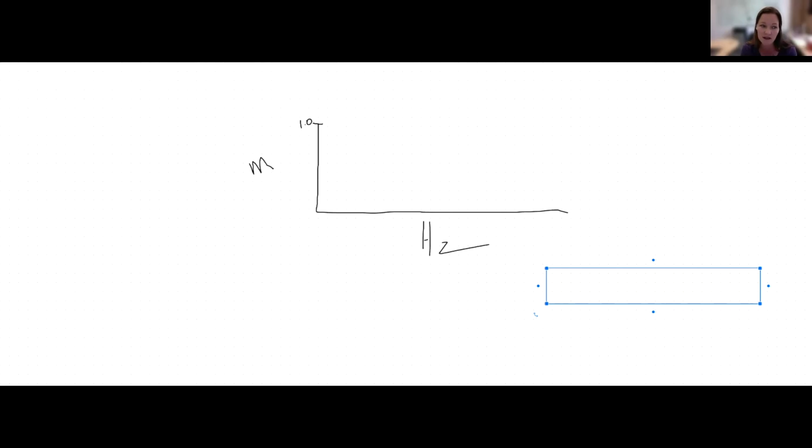Those would typically be at the frequency ranges of the motion, and so they're at lower frequencies, like below 25 hertz. The other common source of noise that you would find in many signals is electrical noise by picking up the AC line voltage, which is at 50 hertz or 60 hertz, depending on which country you live in, right? Here it's 60 hertz, in the UK it's 50 hertz. But that means that you would have a characteristic noise that's oscillating around that frequency in the signal, okay?